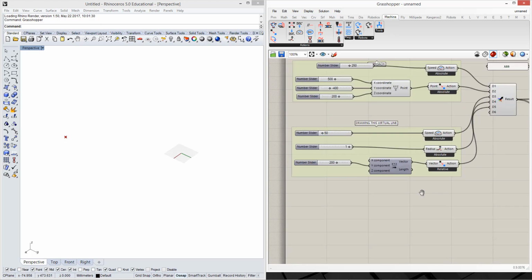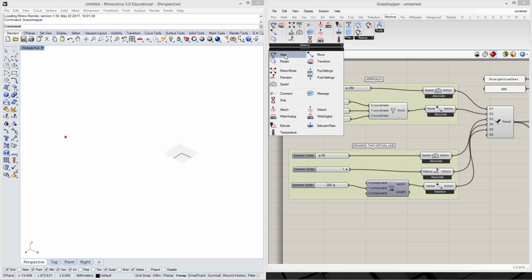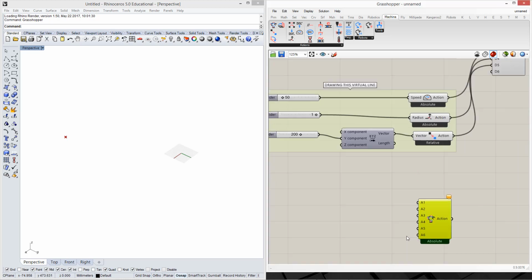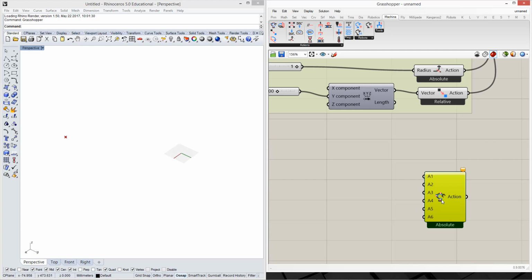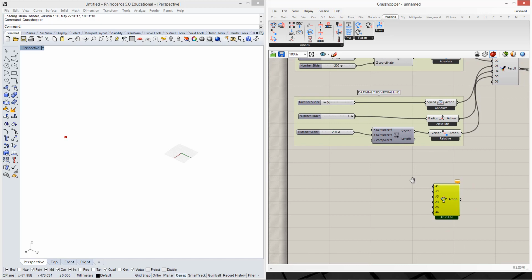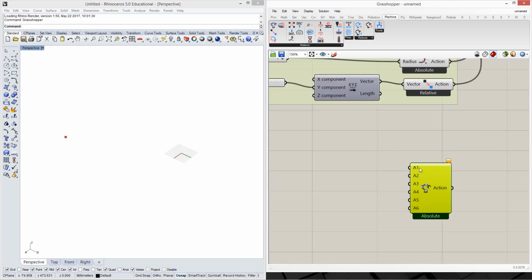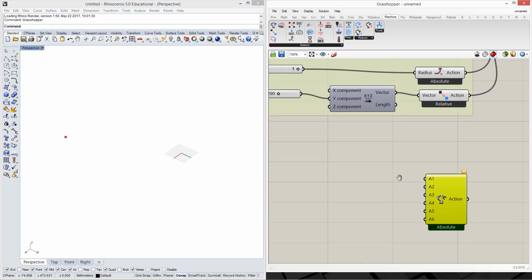And then after that, we may want to move the robot back to a relaxed position, to a home position. Since we're not really clear what the actual XYZ coordinates are, we may estimate them, and that's a good thing to do. But instead of that, we can use the axis component to manually set the angular rotation of each one of the joints of the robot. And I can tell you, for example, that for ABB robots, it's usually this position that we have here, where all the angles are at 0 degrees, except for axis number 5, which would be at 90 degrees.